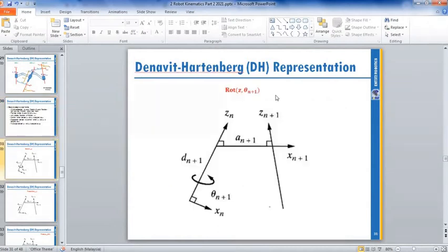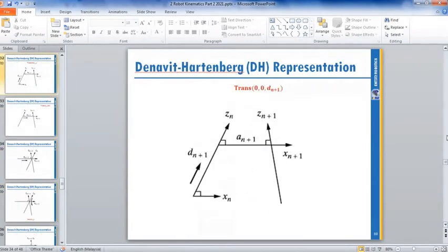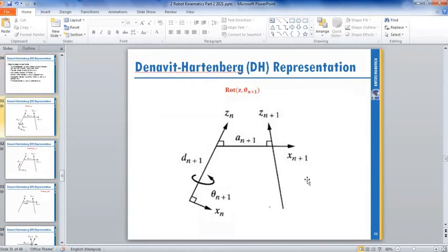Okay, this example. If you found a rotation, after you combine all these, how do you define the DH method, using the DH method, for example? If you have rotation along the z axis, we call it theta. So you use your homogeneous transformation matrix, rotation z. You use back your homogeneous transformation matrix.